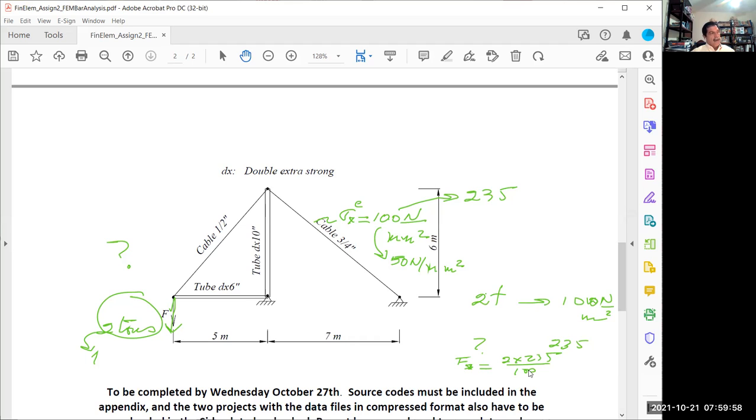For example, when you started to study stability of the ship, you said GZ is equal to GM times theta. But that doesn't mean that if you go to 90 degrees, GZ is going to be GM times theta. No, because that's valid only in a certain range, in the linear range. In this case, we are not saying anything about the limits. So that's why we can apply linearity directly.